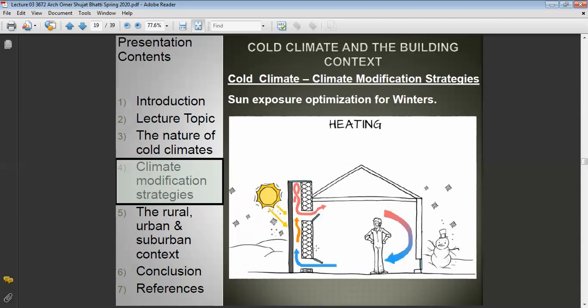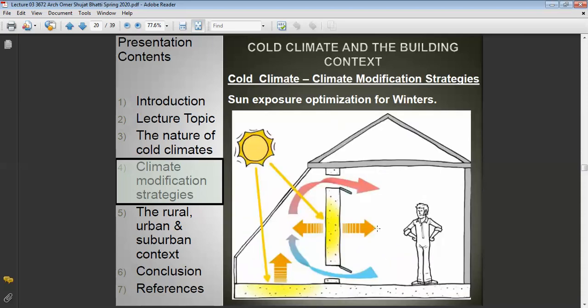Otherwise, once these forms of insulation are in place, the internal heat or temperature can be retained for a comparatively longer time if insulation is provided in a proper way. This is another way of doing the same, like creating a solar room along with the Trombe wall. Both methodologies combined can be very helpful, specifically in areas where the space is not directly exposed to the sun, or it is recessed inside, or the volume is comparatively bigger.